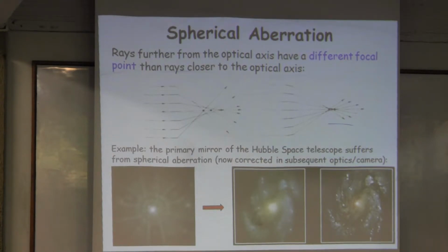So they had to use a correcting lens to make the testing of the mirror simpler. That setup of the correcting lens was misplaced by 1.3 millimeters, I believe, and no one had tested the test setup carefully. So it was a perfect mirror according to an incorrect test setup.